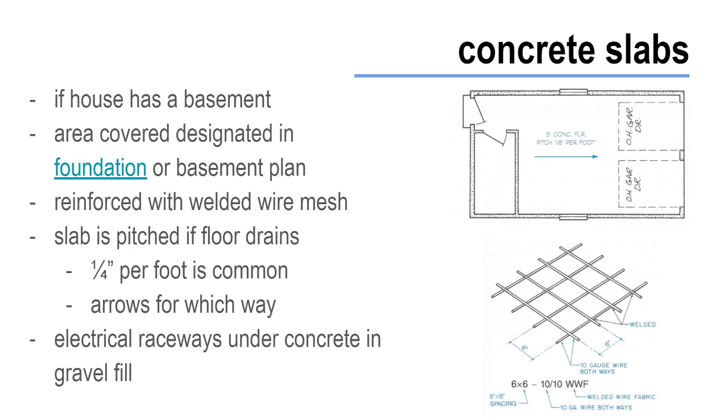Last kind of note about slab foundations is that they may also require electrical raceways to be installed in the foundation, or rather just below it in the crushed gravel fill. They must be made so that they don't reduce the structural integrity of the concrete slab, and you have to keep in mind how large an electrical raceway you are installing in there.